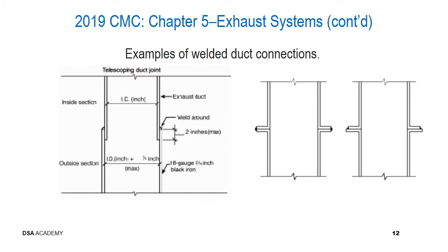And it's required that the joints, whatever the joints are, be externally welded. Those are generally required. However, it is permitted to also internally weld any of these joints, provided that the finished joint is smooth and it's also readily accessible.